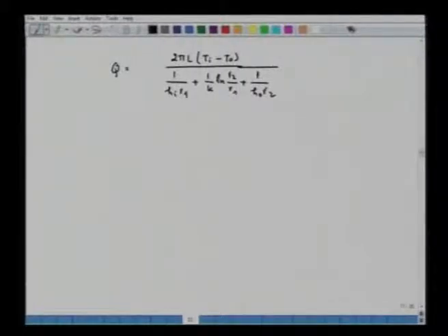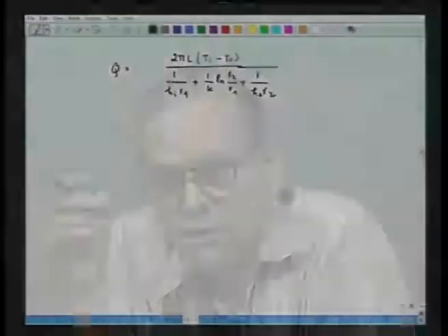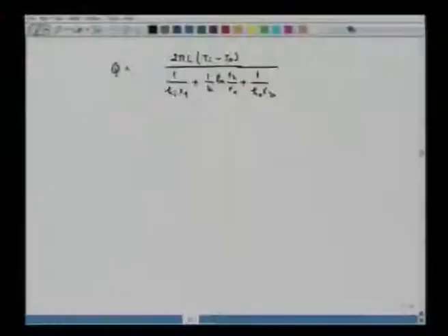And now, if you look at this equation, R2 represents the distance from the center of the furnace to the insulating lining. So, as R2 increases, the value of 1 upon H0 R2 decreases. That is, this 1 upon H0 R2 is the thermal resistance.